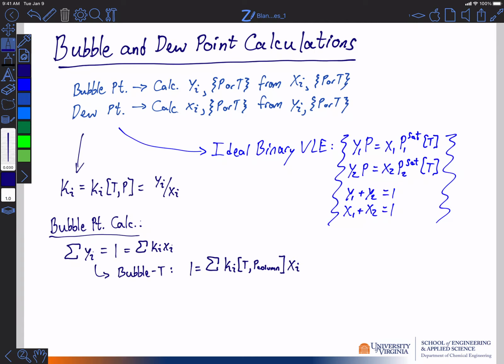And so in going through and doing this, then for as many components as we have in the system, we could write out the number of terms we need on the right-hand side of the equation. Remember, go back to Wankat equation 2-28, right, to refresh our memory about the fact that for systems where we know the K values as a function of temperature, ultimately that K as a function of temperature is just some mathematical expression where T is the only unknown.